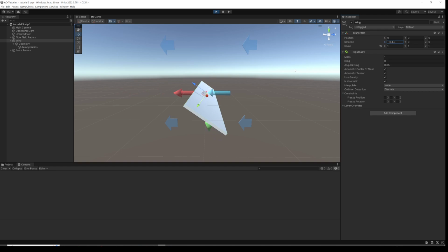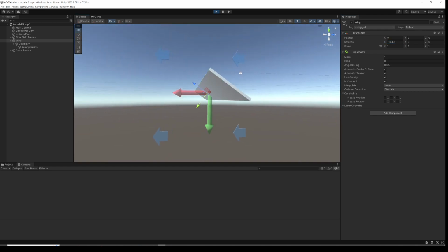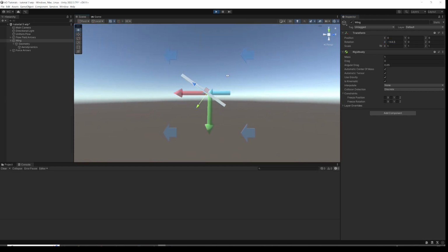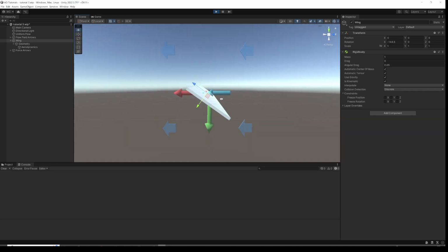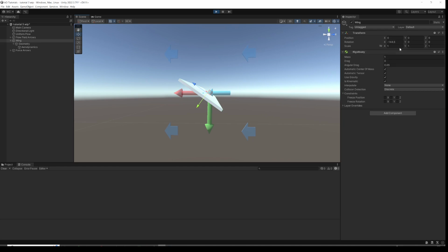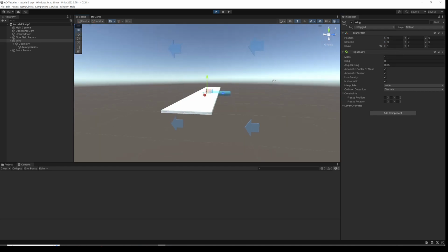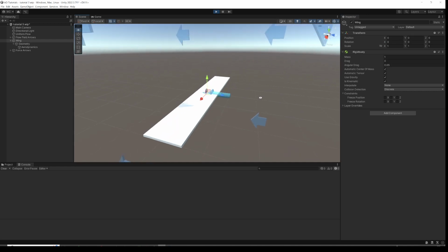Aerodynamics doesn't really care which way up things are, so now this wing is upside down and we are producing lift in the downwards direction. So if we're doing a loop-the-loop, this might be the top bit of the loop-the-loop, and we're actually producing lift downwards, and that's absolutely fine. Reset that. Okay, so what else can we do?